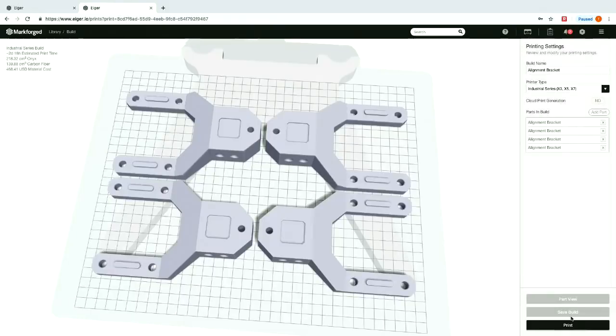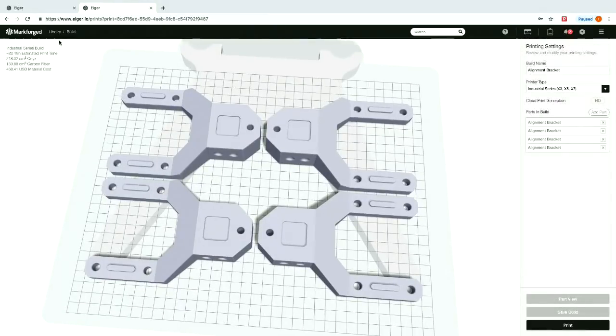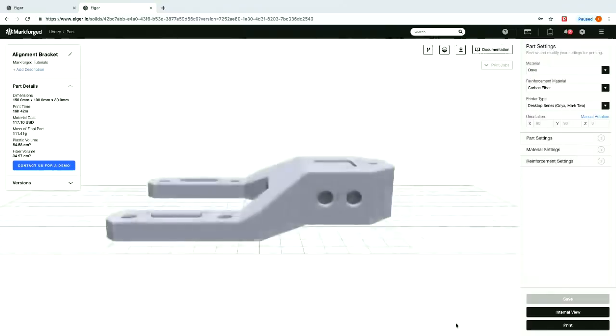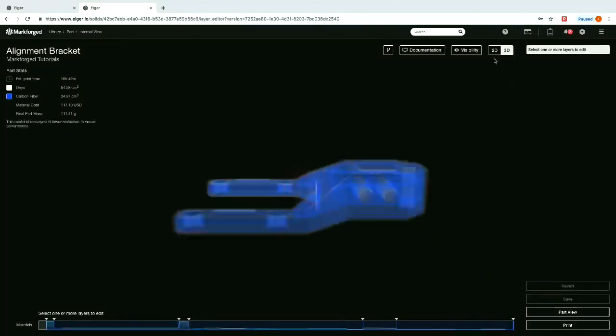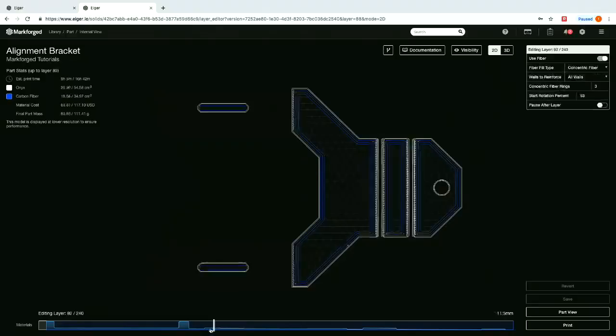Our unique aspect of this is that if you look here, what the fiber is actually doing in the 2D view is replacing this triangular infill on the edge. The triangular infill is this normal stuff here, and the fiber replaces it on this edge. If you have layers that are not reinforced with fiber, you'll see that the triangular infill goes all the way to the outside. That's the unique part of the Markforged system. One thing I also wanted to note, this part doesn't have too many supports, but these here are just a hint of same material supports going through this hole. If you have a part that needs supports, it will auto-generate them for you.